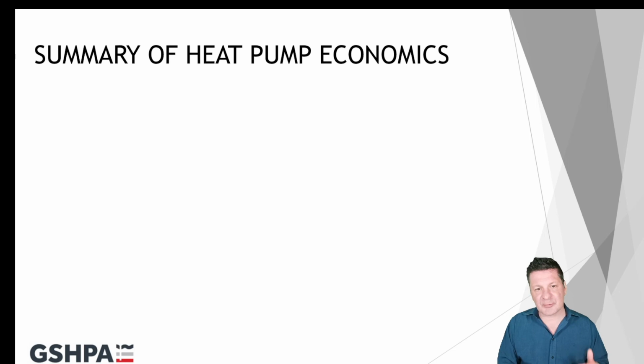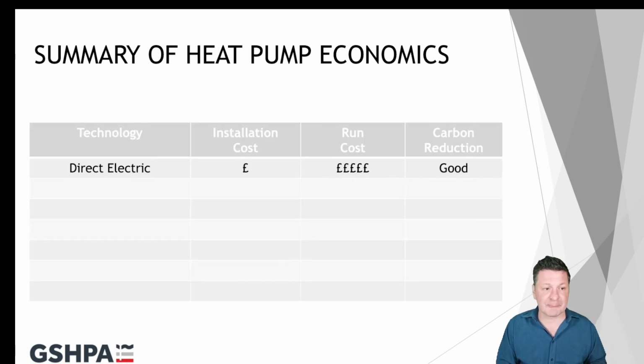So let me just give you a summary of the heat pump economics by source type. Let's compare it to a direct electric system. So underfloor direct electric becoming more common, storage radiators, that kind of thing. Installation cost is very, very low. Hence, it is very attractive to developers who have got an eye on that low initial cost of the system.